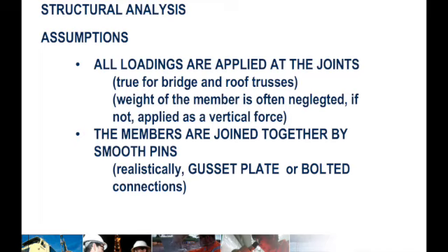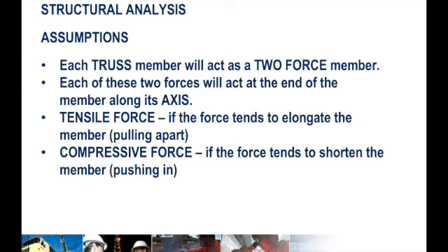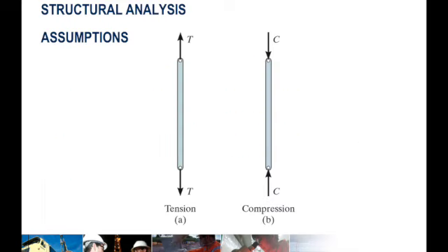So the same assumptions are still in place. All loadings are applied at the joints, and the members are joined together by smooth pins, and each truss member will act as a two force member, and we will be determining if the force in each member is tension, tensile force, or compression, or compressive force. So this is what our truss members should be subjected to, either in tension or in compression.